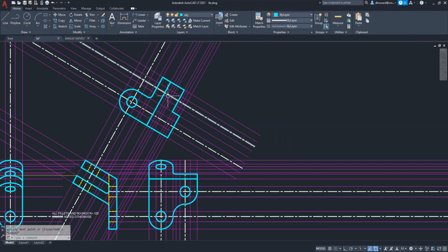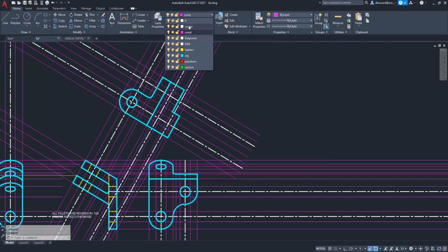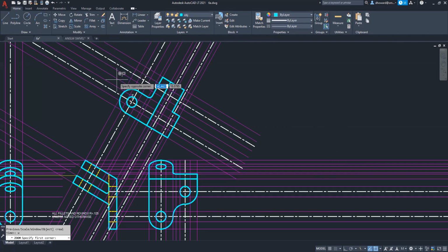We need to put in the holes here, which are ellipses, and the outer circle, which is also an ellipse. And then this inner curve, which is an ellipse. So let's mark the centers here with actual center lines coming out of these. So I'm going to click on both of those guys and say, those are the foreshortened view center lines. There they are. And let's get on it. I'm going to zoom in there tight so we can do this.